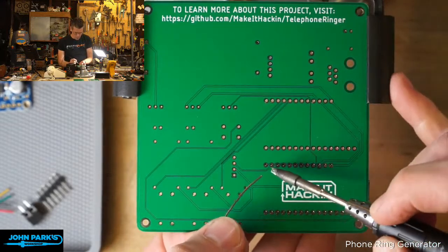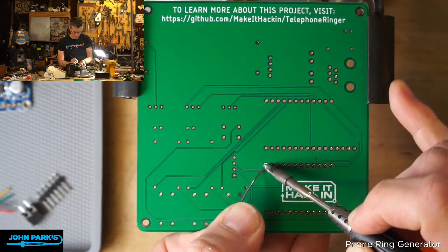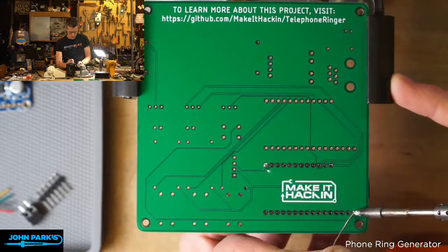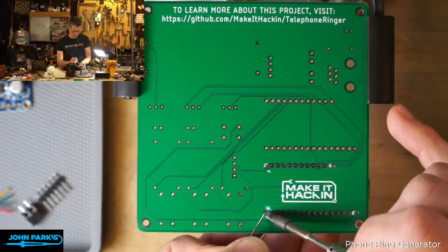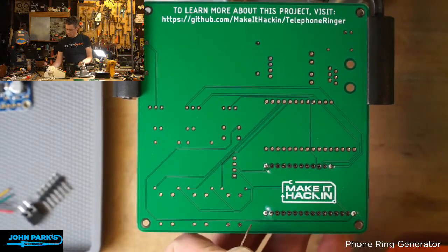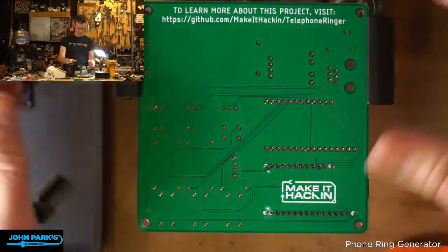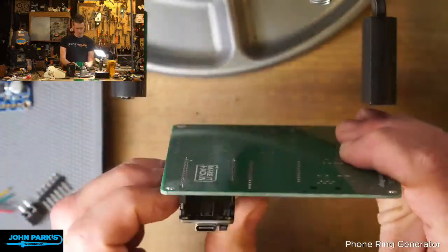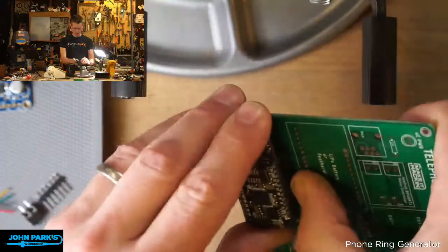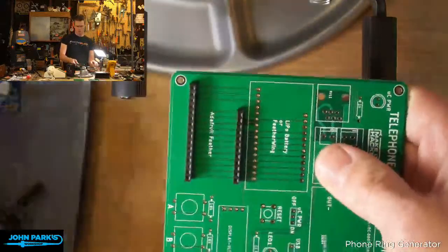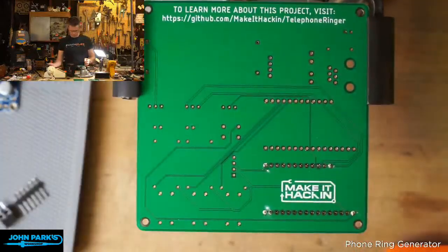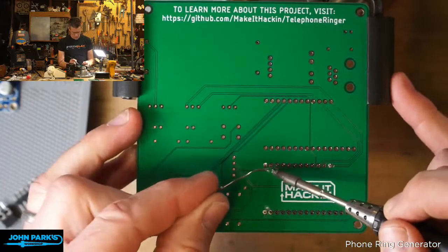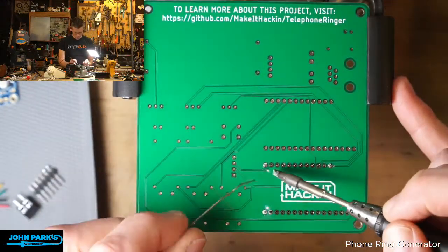Let's get this started. I'll usually solder in the corner pins on these to get going, and then you can double check that nothing is super wonky before you go soldering the rest of the pins in. So that looks good. My feather itself was in a little crooked, but it doesn't matter. The little feather headers are on there nicely. I really love this design. It sort of puts it all on one level, one layer, and since the feather is small but super capable, it gives us a lot of room to work with, which is great.